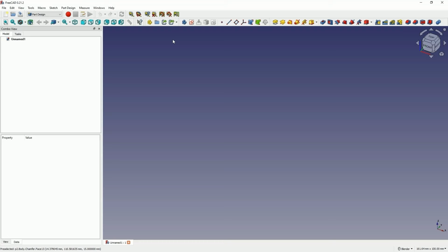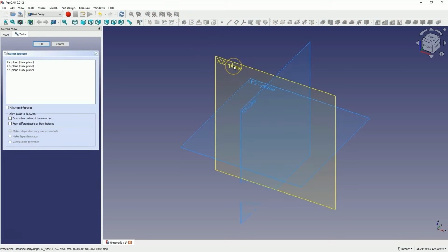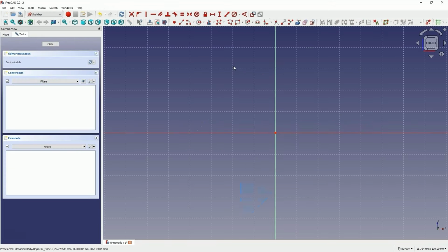The next basic operation for creating 3D solids in 3D CAD systems is to create a solid by rotating a sketch around a specified axis. We will now create another sketch, select Sketch Creation and choose the XZ plane. Then select Rectangle Drawing, and we will create a rectangle whose first corner will lie on the X-axis. Once the X-axis is highlighted, click at this location and place the second point approximately in this location.